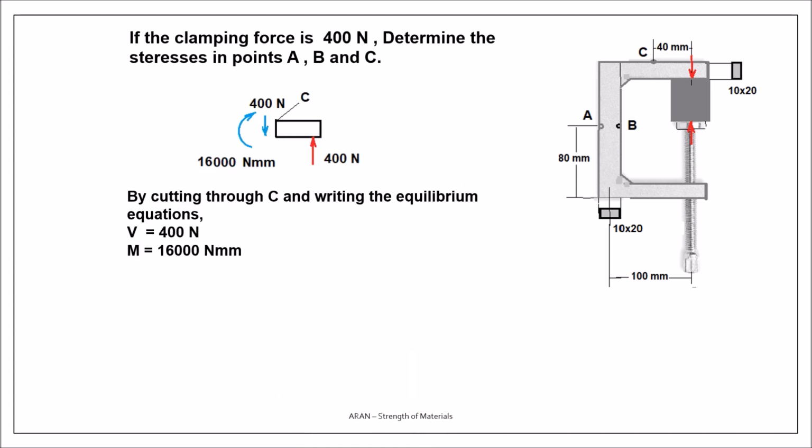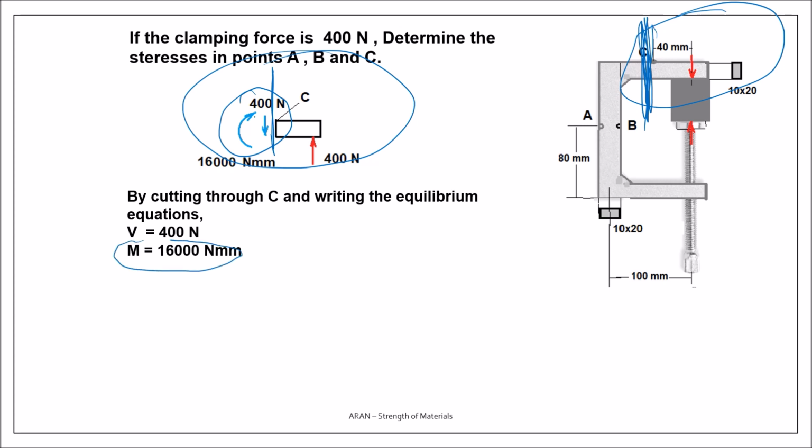Well, next we have to consider this section. I cut here and take this part, and draw the free body diagram. Now my internal forces are a bending moment and now a shear, and shear is a force acting in the plane. So let's try to find the stresses in point C.